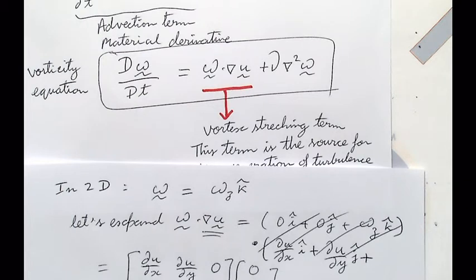Very conceptually, people used to think about this as a cascade of vortices. Bigger vortices get broken down into smaller and smaller vortices, and eventually, when the vortices are small enough, the diffusion term is strong enough that it can kill them. That's the basic idea behind turbulence.